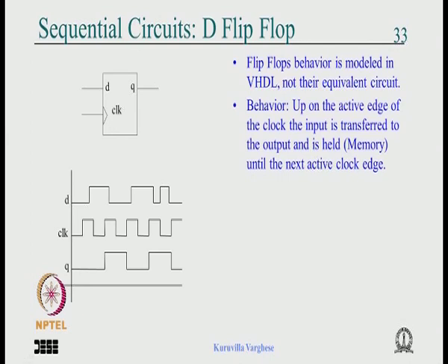So as far as the combinational circuit is concerned, we have completed the concurrent and sequential statements. You could start writing VHDL code for various combinational circuits. I suggest you try writing simple things like multiplexers, demultiplexers, adders. I will give some 2-3 examples.